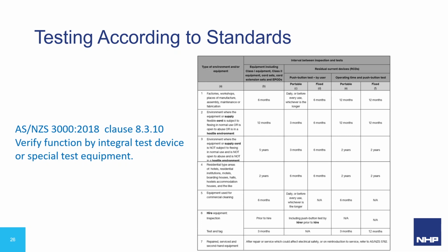There exists an exemption for testing of RCDs in new installations if there is no supply available at the time to sign off, which seems a little bit strange, and therefore this exemption is to be removed in the next amendment to the standard.